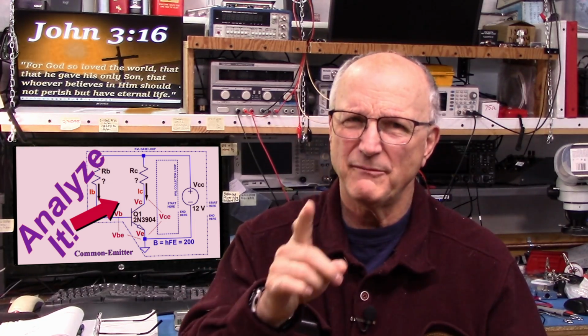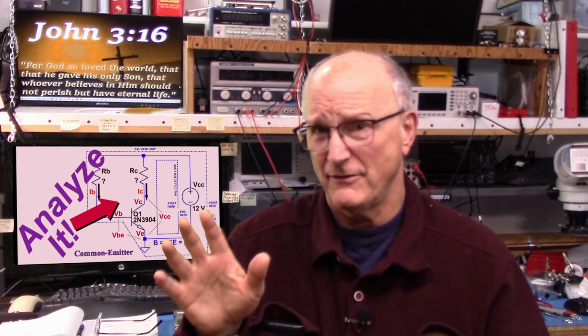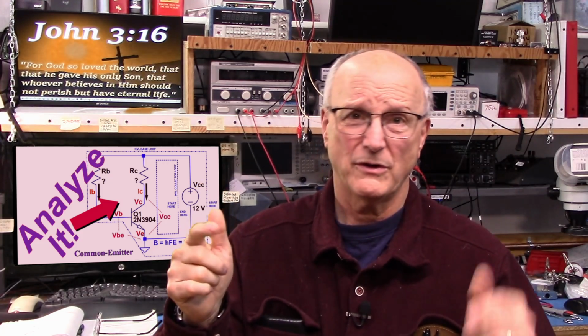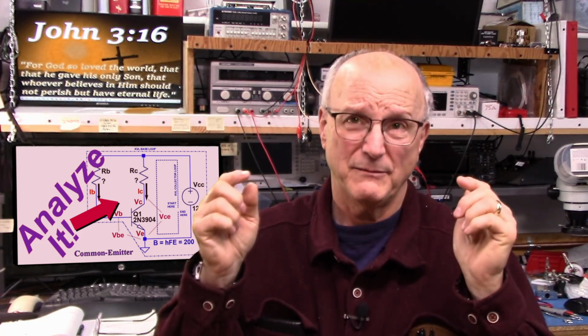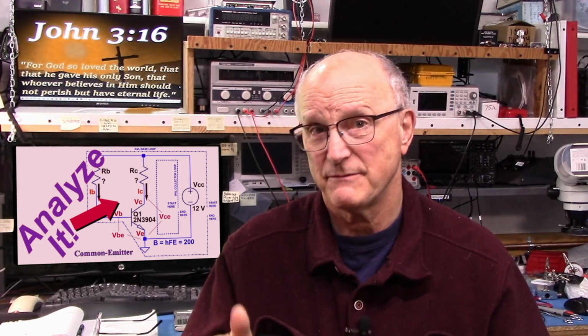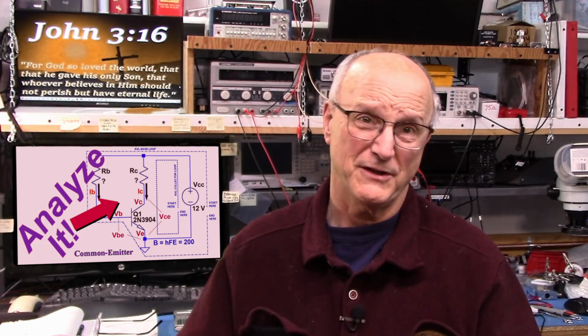Well, I have to repeat my very important additional note that you absolutely must remember when creating a transistor circuit that doesn't live by itself. Anything that you connect to the input or to the output of the circuit becomes part of the circuit. They either become a current source or a current sink that can and will change the operation of the circuit. So pay attention to this.